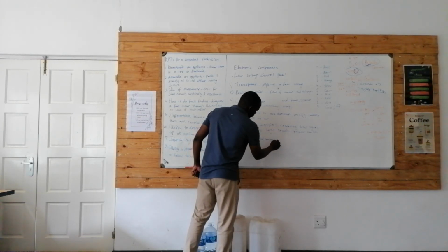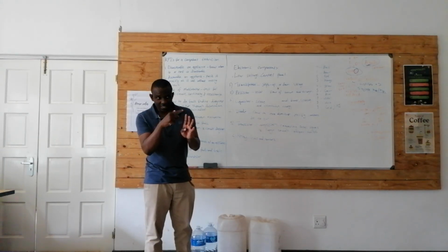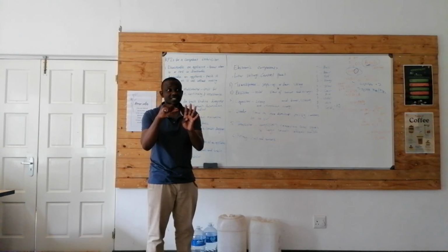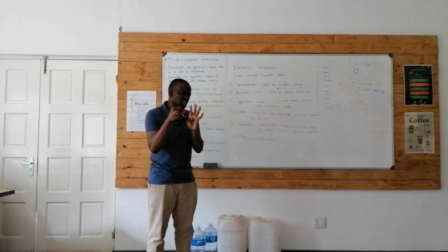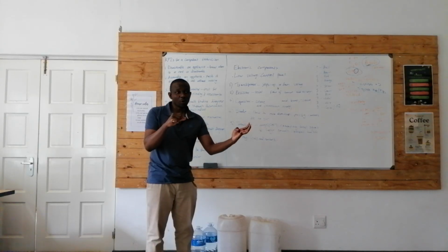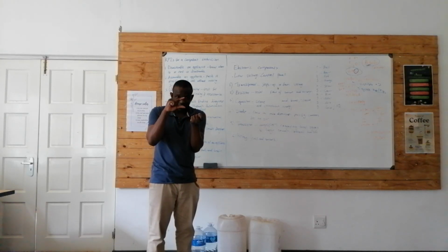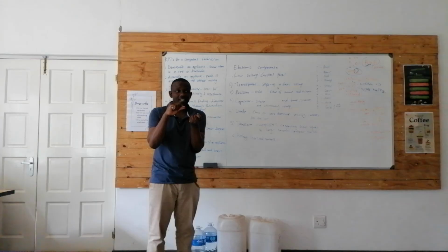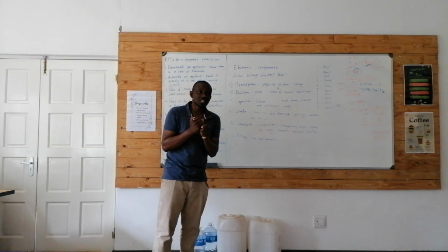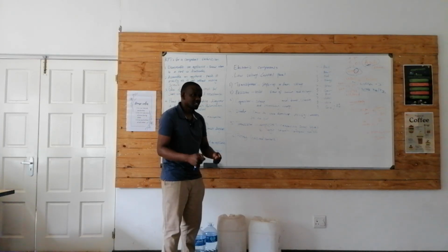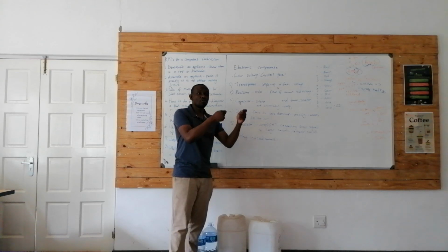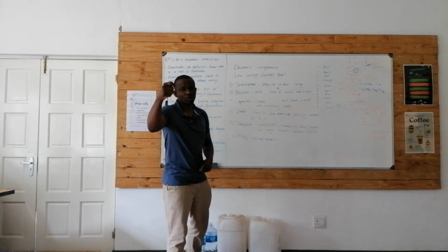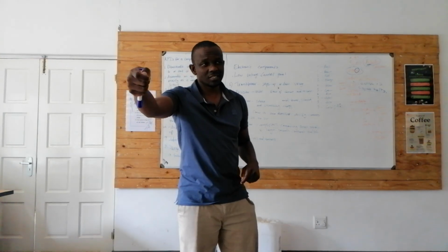In a relay there's a coil and there are contacts. When the coil is energized, the contacts meet. In most cases, relays are found on the low voltage side, but they control components on the high voltage side.